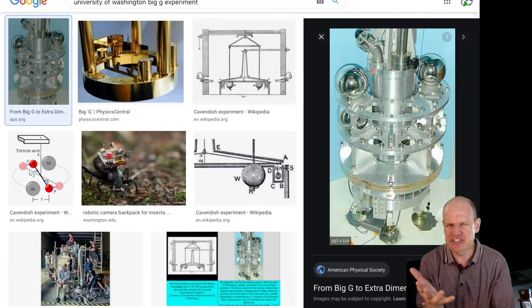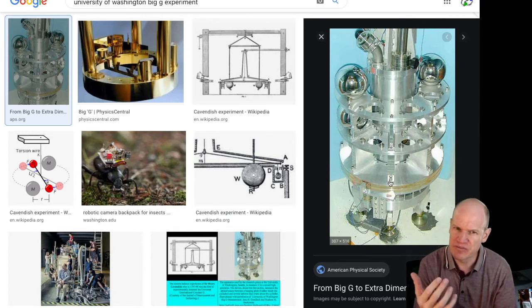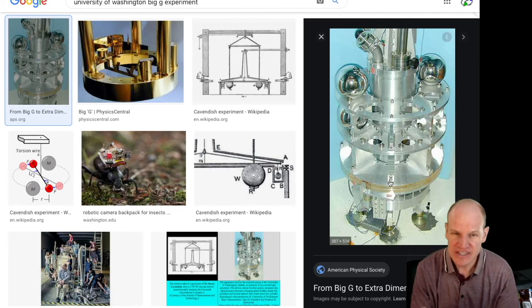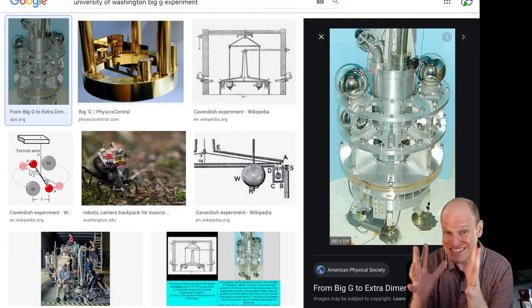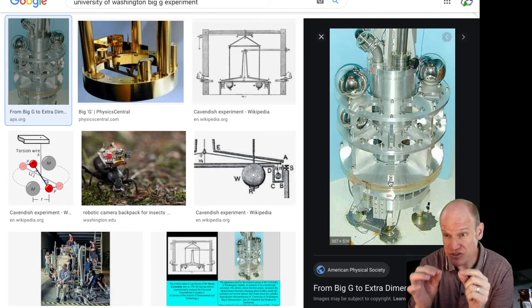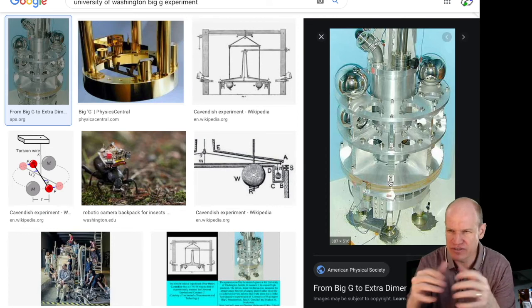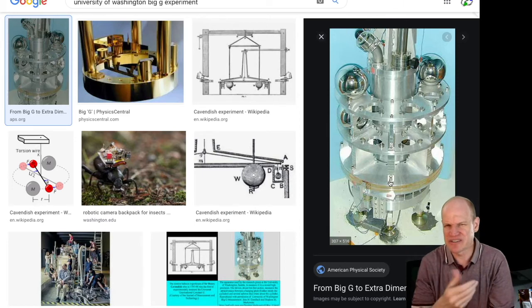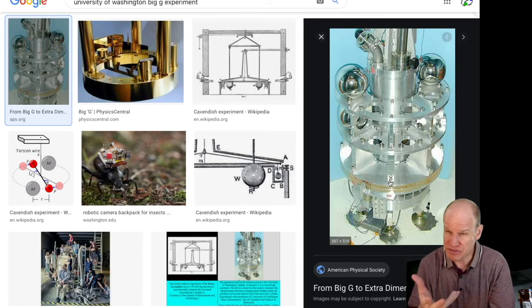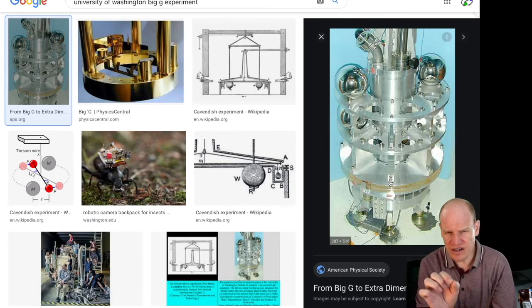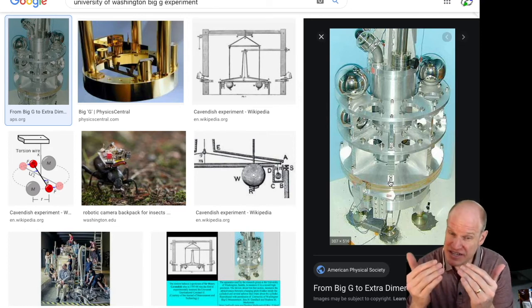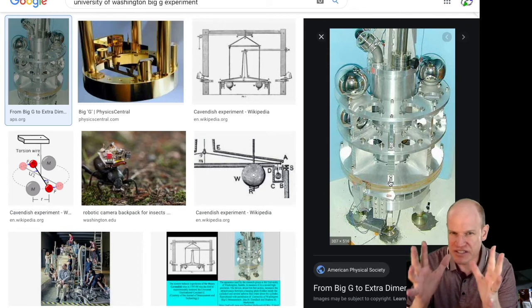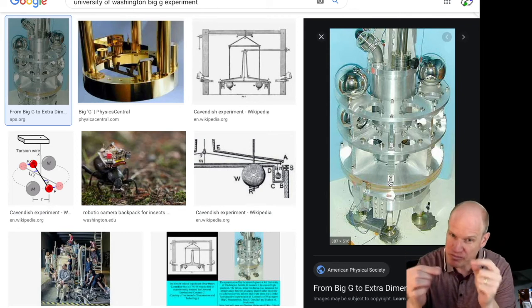There are always going to be machining errors whenever you make something, so you want to identify the machining errors that are going to cause you problems, and then incorporate in the design some way to mitigate them, even with high precision machining. In this case, the machining tolerances tend to be a couple of mils, like a couple thousandths of an inch. But you can even take it down by another factor of 10 if you have some way of balancing it with some movable part of the apparatus.